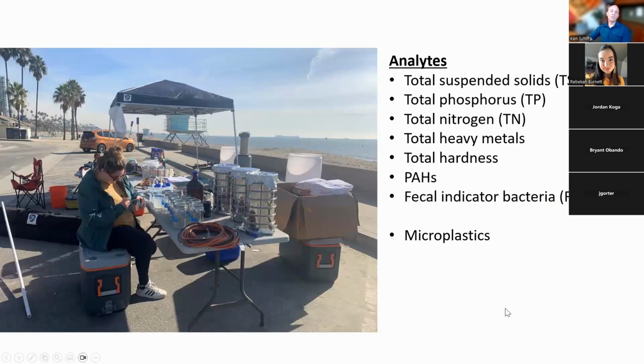And then this picture is meant to show how the sampling goes. So you have this 55-gallon drum of sample. You need to consistently agitate that, either with a manual stirring, or you can put it on a giant magnetic stir plate with a stir paddle. Either way, try to homogenize the sample, and then you subsample for all the different things you want to measure. Here's the list of things we measured, including all the blanks and QA samples.